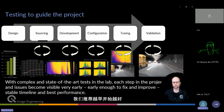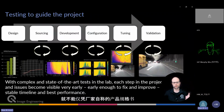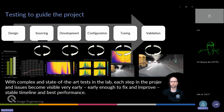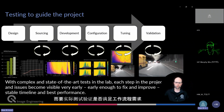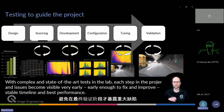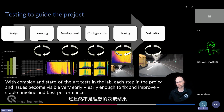So the earlier, the better. If you do the sourcing, you have to decide what sensor to use already then, perform a proper test and not just according to the data sheet. Get it into testing so that you can see if it works for your workflow, for your needs. Only with proper testing can you see directly what works and what does not work, and that gets you out of these nightmares that at the very end, in the validation phase, something comes up, and then the decision is, okay, either we ruin the timeline completely or we ship a bad product. And that's not a decision you want to make.